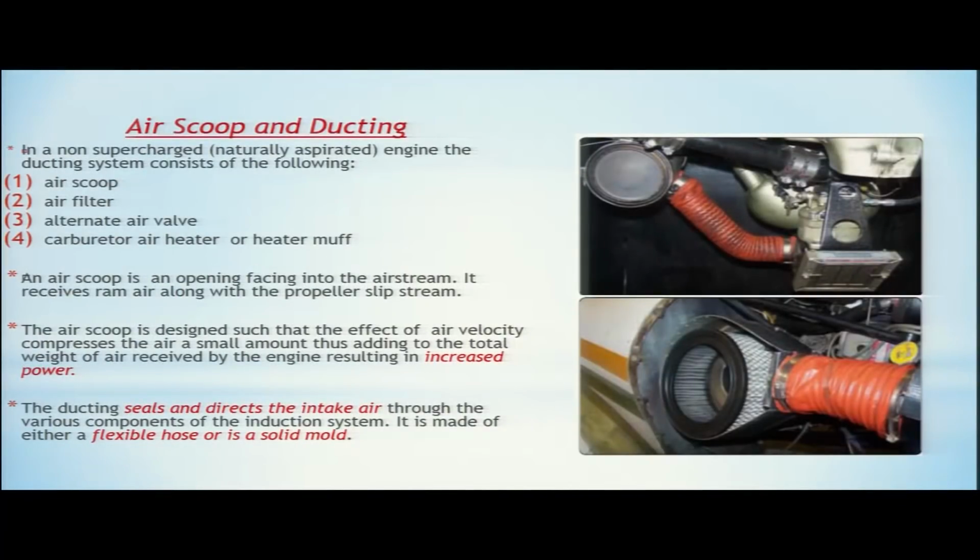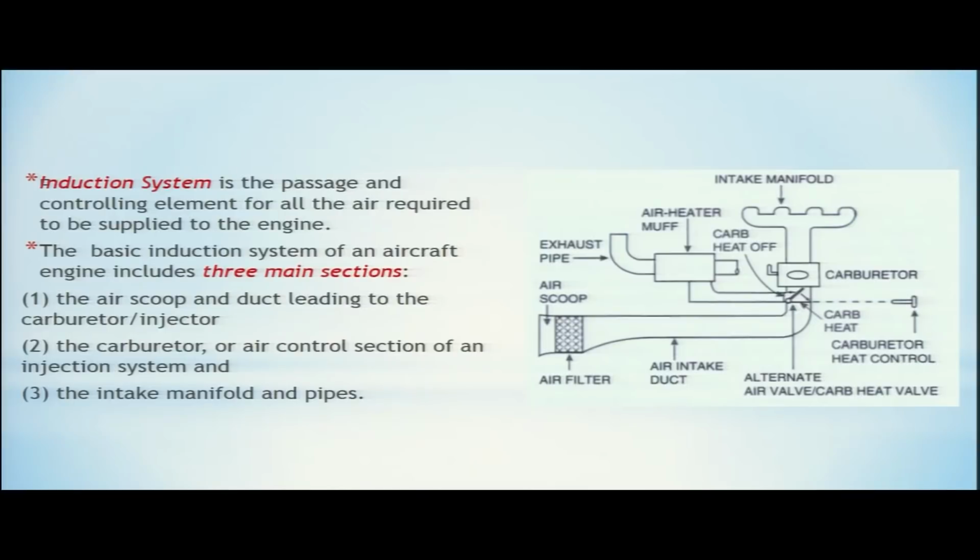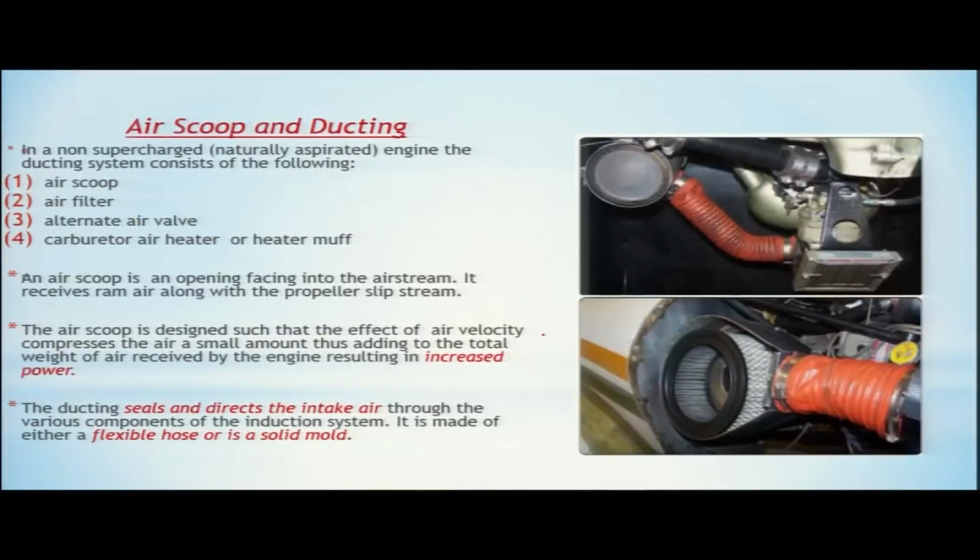An air scoop is an opening facing into the airstream. See in this diagram, it is open from this side, it is an opening which is facing the airstream. It receives ram air along with the propeller slipstream, since it is just in front of the propeller. So it is receiving the ram air from the propeller.